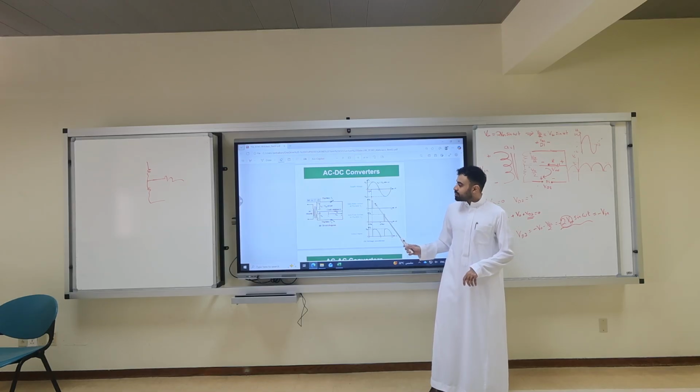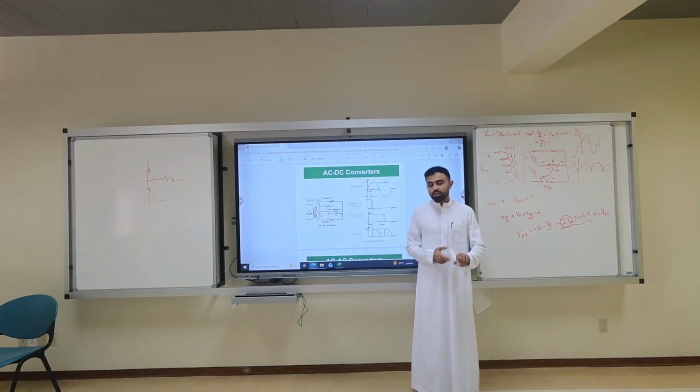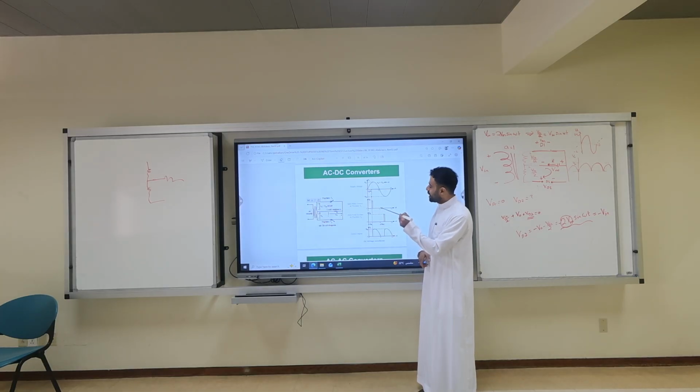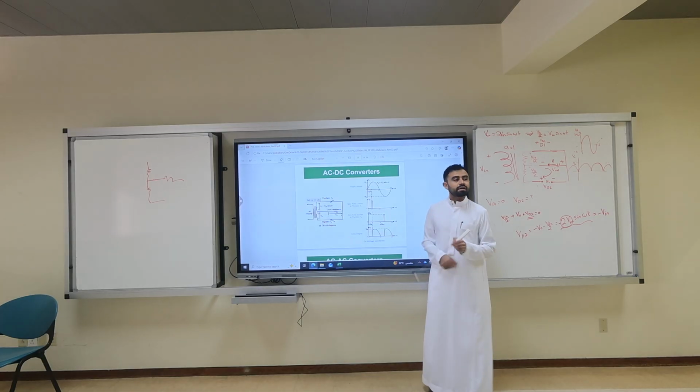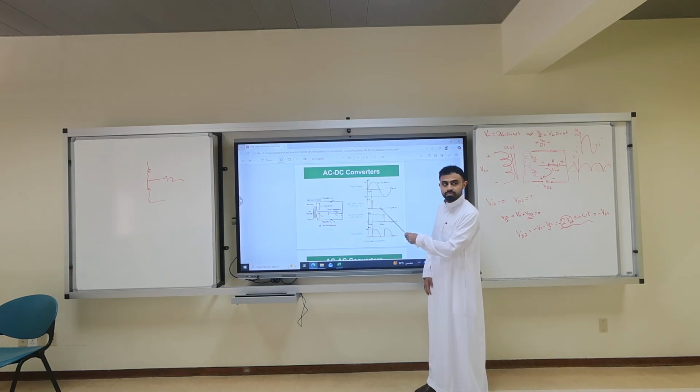So how to make this a regular diode? Fire exactly at zero, and another exactly at pi. No need to have it all the time. If you do the firing at zero and the firing at pi, you will have full wave. But what if you first fire at pi? We will miss out. You will have only one half of the signal.